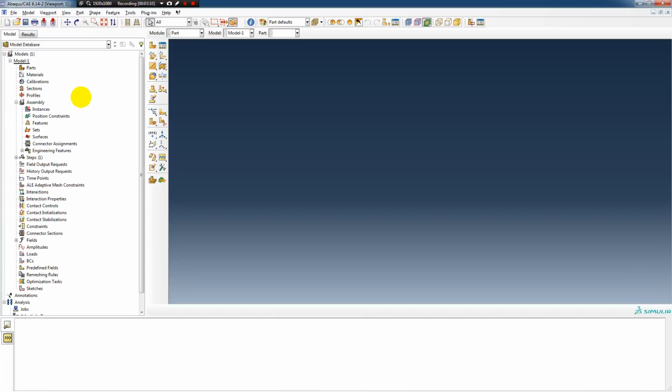You set up your input file using some other preprocessor, or set it up by hand, or I guess in the really old days you'd use a Fortran punch card deck. But those days are past, and so we have this nice GUI. That said, we can still use editing of the input file, or it's called the input deck, to make hand edits and then run those with the solver outside of the graphical user interface that we do see here.